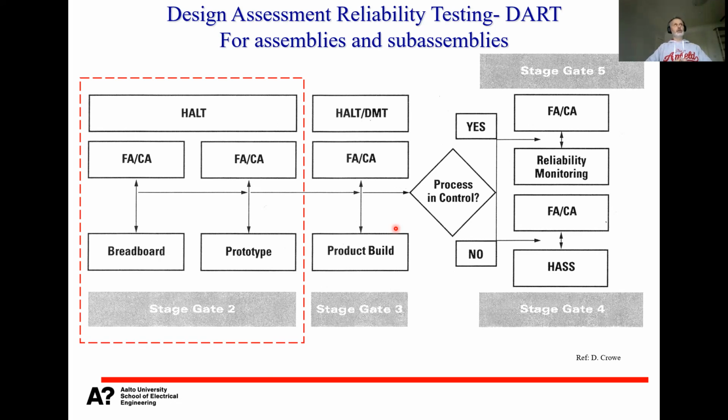Then the manufacturing method could be something different. So for example, you could use printed wiring boards which are manufactured in a slightly different way, because you purchase only a few dozen of those. Your soldering methods could be more simplified. You can use even manual soldering there just to get all your components on the printed wiring board. So at this stage, you don't consider how relevant, for example, the quality of the solder joint is. You just want to see that, okay, did I do something stupid in the design?